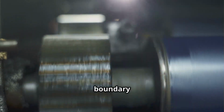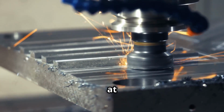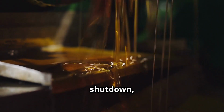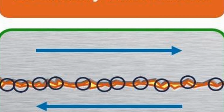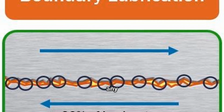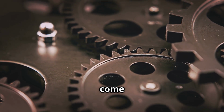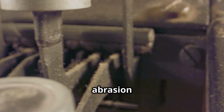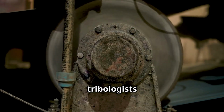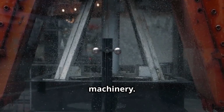We generally want to avoid boundary lubrication where possible. It is agreed among lubrication specialists that friction may be at its highest level during the boundary lubrication regime. This occurs at startup, shutdown, low speed, or high load conditions. Boundary lubrication regimes occur during any condition where the asperities of two lubricated surfaces in relative motion may come into physical contact and the potential for abrasion and/or adhesion occurs. It has been suggested by lubrication engineers and tribologists that as much as 70% of wear occurs during the startup and shutdown phases of machinery.